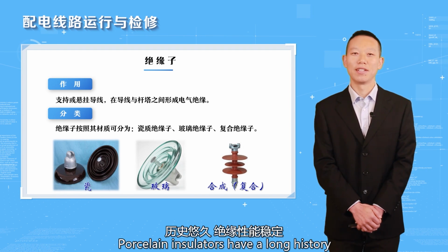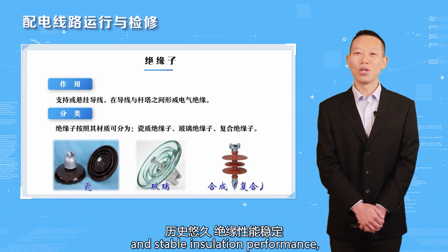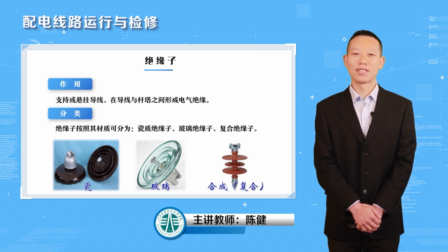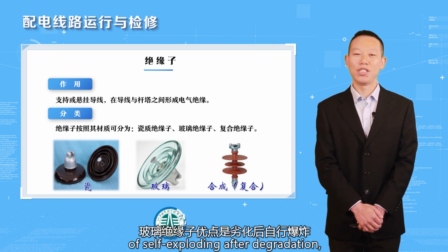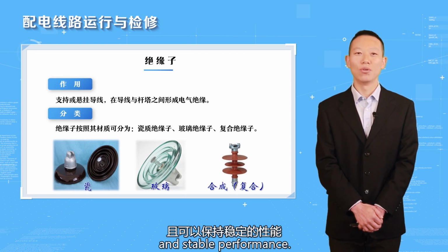Porcelain insulators have a long history and stable insulation performance, but defects are not easy to detect. Glass insulators have the advantage of self-exploding after degradation,